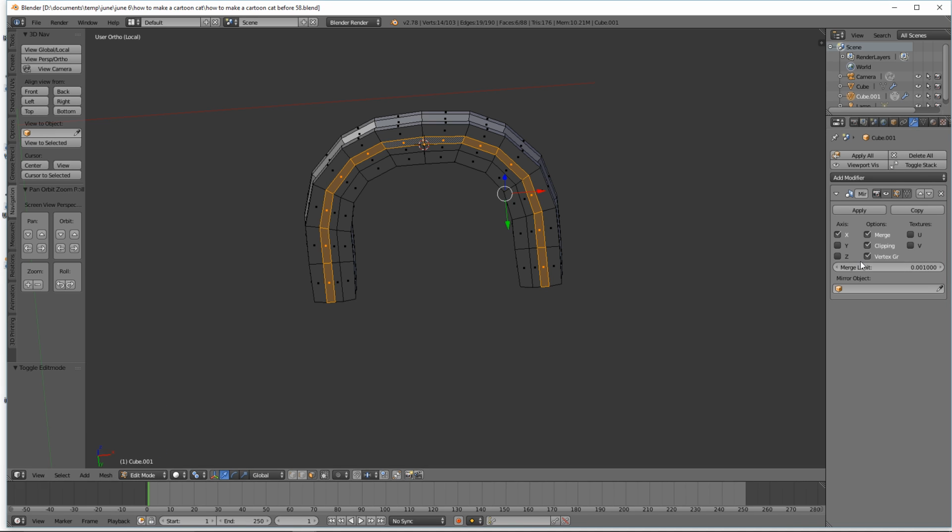Okay, what we're going to do is click here to temporarily not have this clipping activated. Now we're going to hold Alt, and while holding Alt, press E. This brings up our extrude menu. We're then going to click individual faces. I'm then going to right click. We made new geometry. Doesn't look like we did anything.